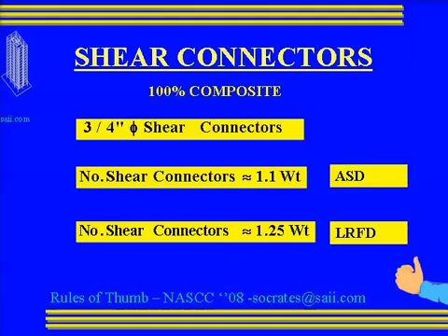Here's something else. A lot of times erectors and fabricators want to know how many studs you have in here. They like to hear them in studs per square foot, or in some of the parts of the world I work with, how many studs per square meter. And if you're ending up with more than 3 studs per square meter, something is wrong with your design. Sometimes they start telling me, oh, we figure 10. I say, oh, no. But here is a good approximation.